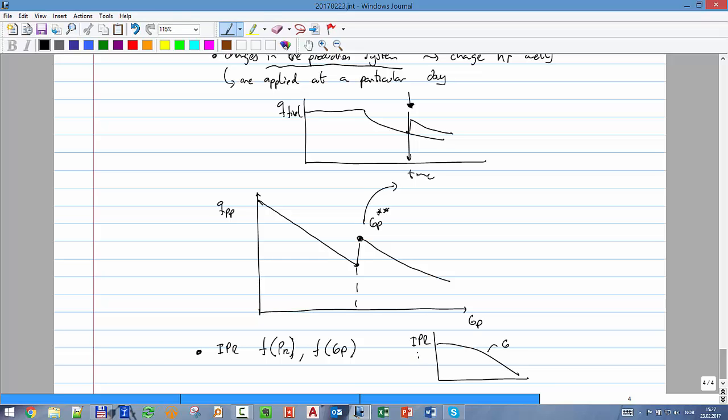Yeah, let's leave injection for one moment. But imagine that you have a horizontal well, and you have the oil layer and you have the gas layer. One of the main issues with horizontal wells is that if you lower the pressure in the wellbore to a critical value, you will have coning, right? So you have to be careful all the time that PWF is higher than this critical pressure, which we call the critical coning pressure.